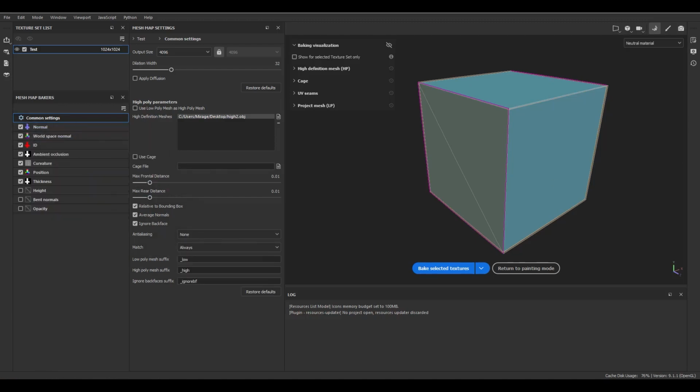Anti-aliasing can help us to increase the quality on the mesh maps, especially when we have a diagonal line like this, because at the end we are going to record all the data into the pixel, right? And when we have a diagonal line on this UV on the pixel, we have some jaggy effect. So we need anti-aliasing to remove this effect and increase the quality.